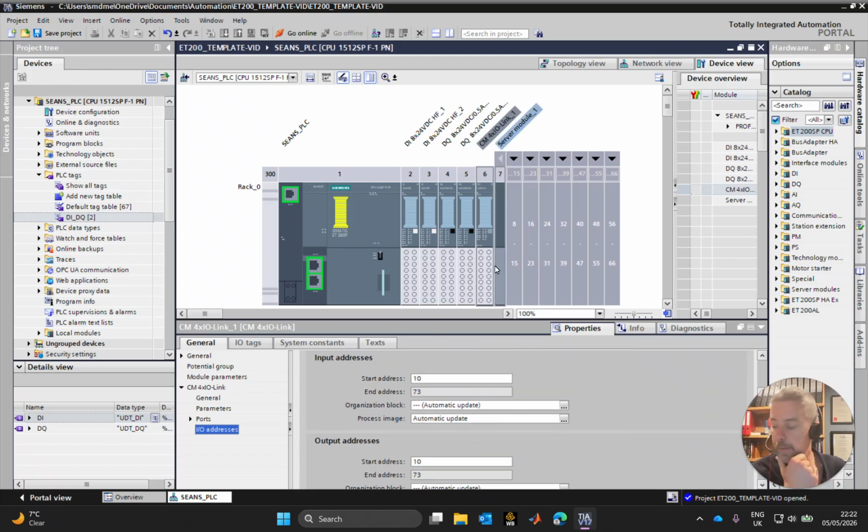Now, IO-Link devices could have inputs and outputs in the same device. Some might only have inputs, some might only have outputs. So this is an example that only has outputs. There is no inputs in this. So any output data, output memory that I have for this will be starting in %QB10 or %Q10.0, into this device.